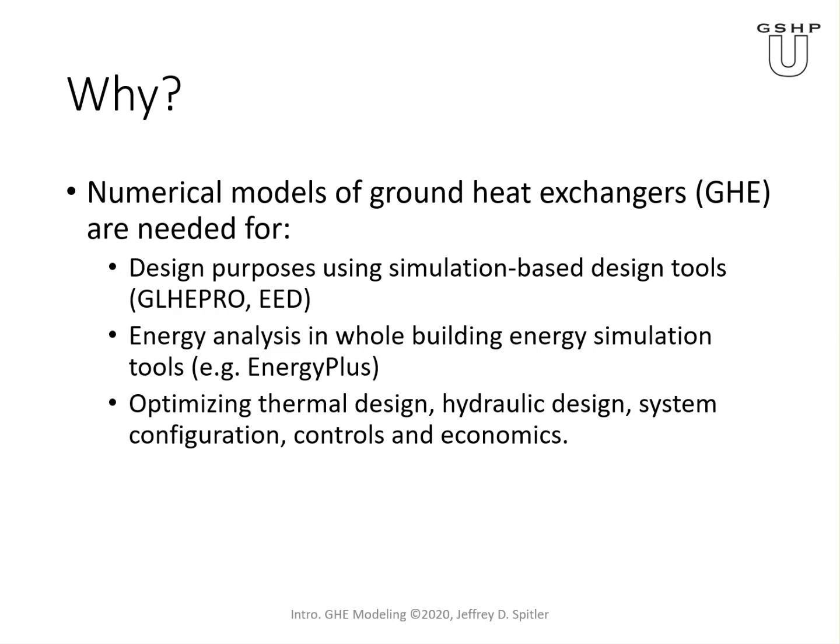We need this if we're doing energy analysis and whole building energy simulation programs like EnergyPlus or eQuest or other programs. We need some sort of model to predict, if nothing else, what's the fluid temperature coming back to the heat pump or heat pumps.